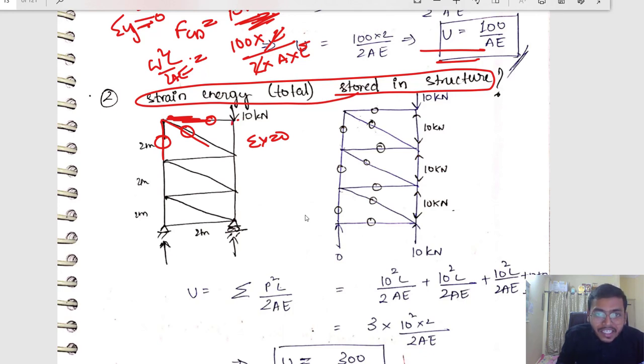So this was 10 kilonewton, so I got compressive force like this. Again, two members are meeting collinearly and a third member is coming and no external load, so again this is a zero force member. This continues just like the above terms and all these members will get 0. Very similar, very simple, right?